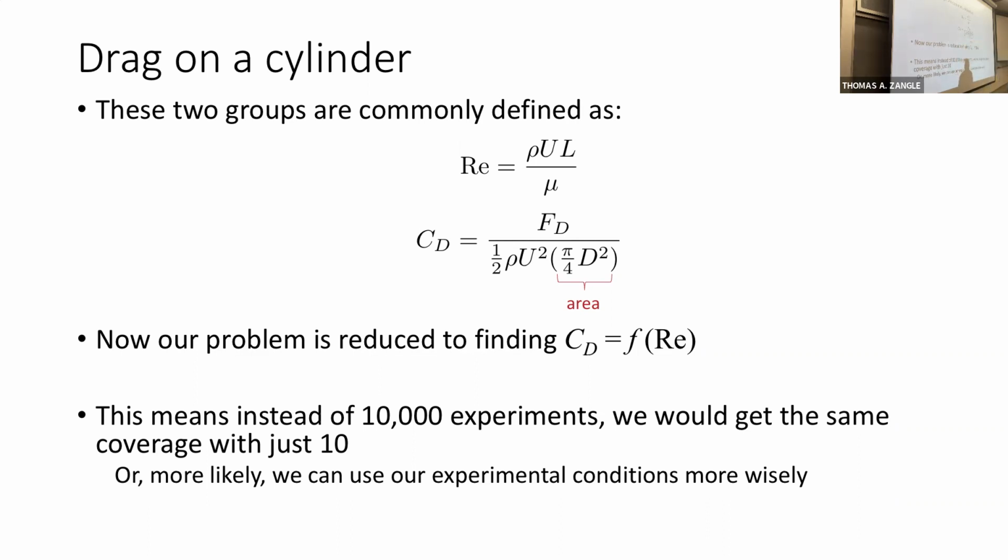So in this case, roughness would be another independent variable, right? So we'd have to increase the number. We would not be changing the number of dimensions, because we still have MLT. And so we'd end up with coefficient of drag as a function of Reynolds number and epsilon over d. And then when we went to run our experiments, we would now have to vary both Reynolds number and epsilon over d.